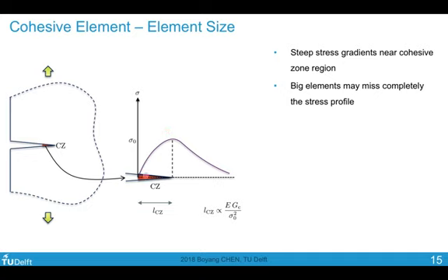And if you use very big elements, for instance, one node around here, and the other node very far at the back, what you get from your evaluation at the integration points and the interpolation using linear shape functions is a very underestimated internal force and external force vectors. So the internal force vector, which you evaluate at this left end and the right end, misses the entire rising and following part of the curve.